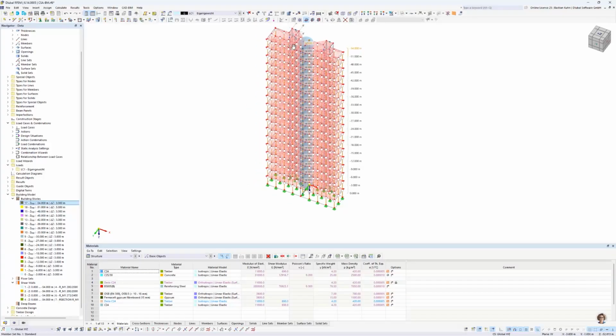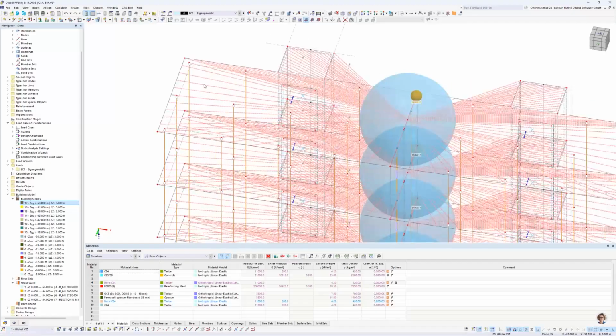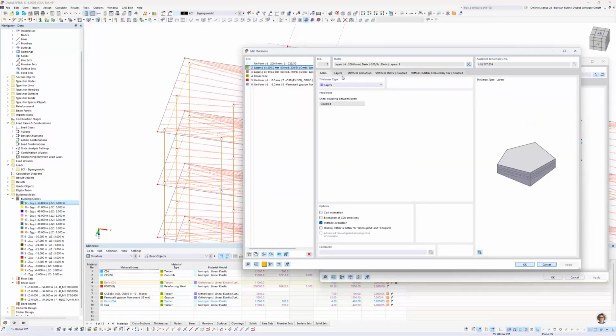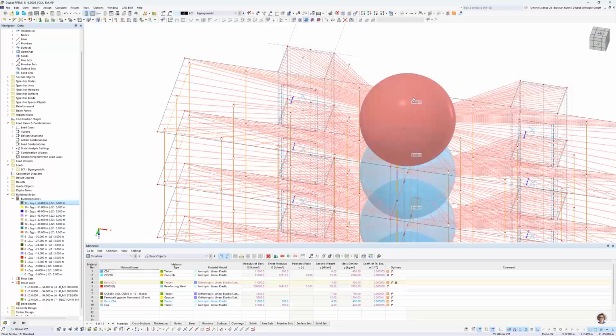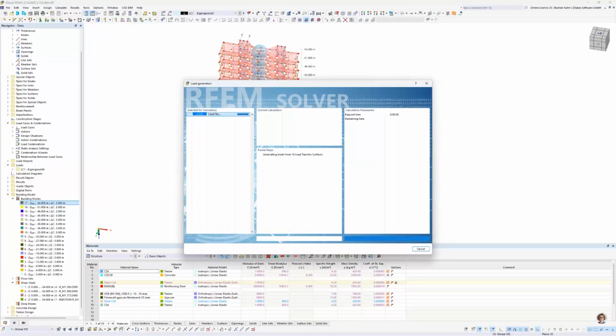Right? So the difference, I mentioned it already, from semi-rigid to rigid is that now it has a very high stiffness in the area. There's not any more the stiffness that is calculated here. So, but each FE element is connected to the mass center with a rigid member, which has hinges on its end. And we can also calculate this and take a look.